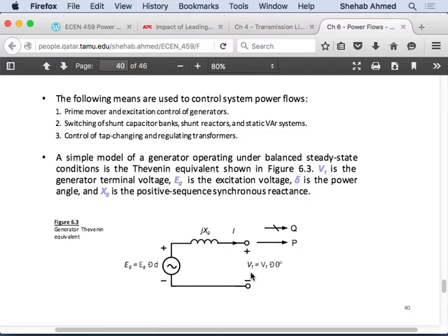They will probably affect you. I mean, the power that they are providing is much bigger, right? So we will assume that a new generator wants to come in and synchronize with the grid. I will assume that I have to meet a certain voltage and angle requirement, right? That's how you synchronize in the experiment in 338. You brought in a generator, you made sure that the voltage and frequency were exactly the same, and then you closed the switch, right? So that's synchronizing to an infinite bus sort of example. And that bus is your reference.